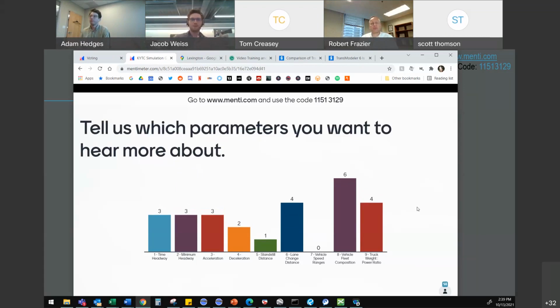Maybe there might be a connectivity bias between freeway and non-freeway links, whether or not people are more willing to take the freeway versus stay on an arterial. Those types of things you can't necessarily measure in the field and are used in DTA and might need to be adjusted, but aren't included in those nine parameters.